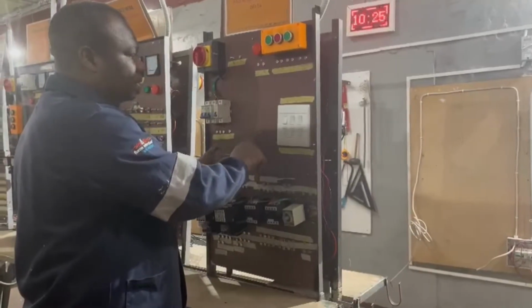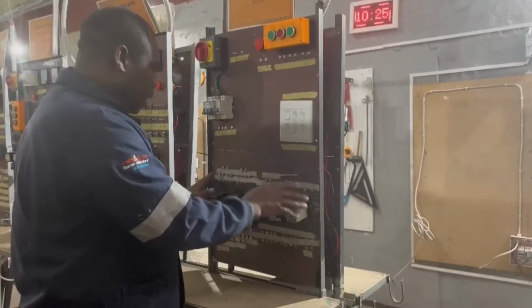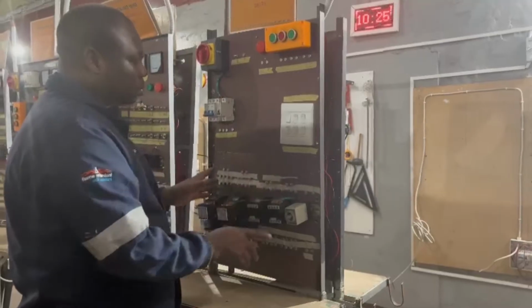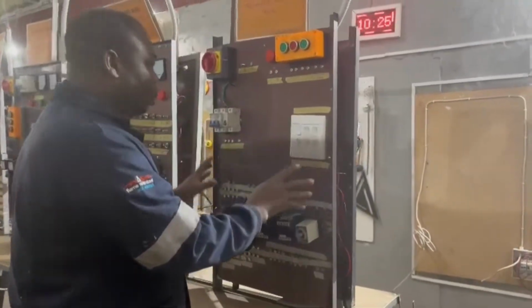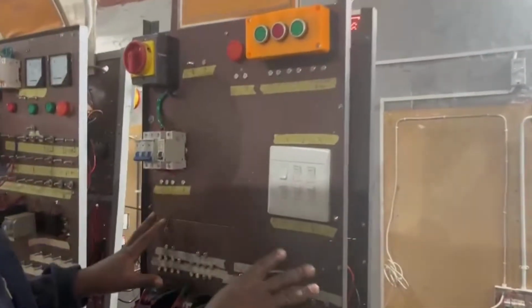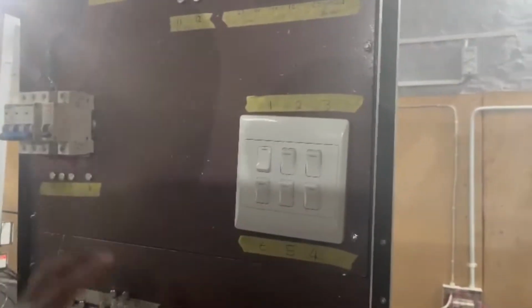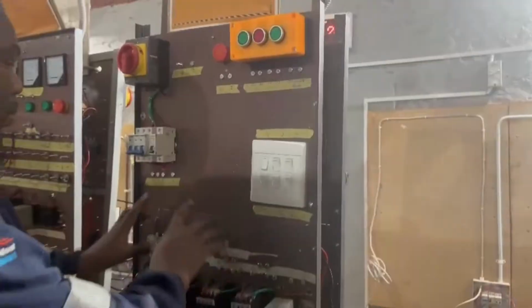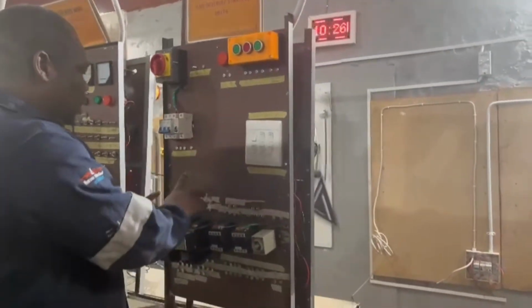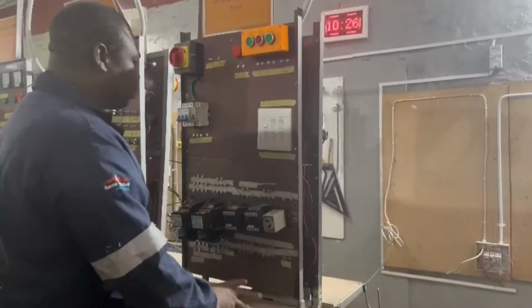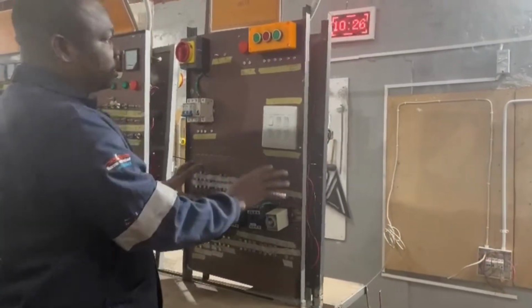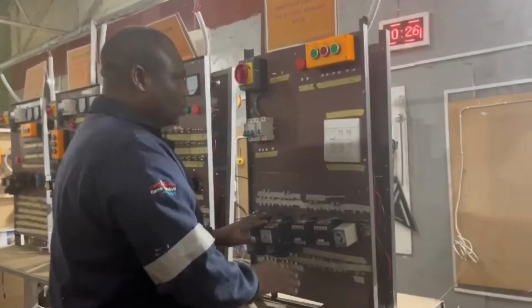So the fault here is just an open circuit fault, whereby when the switch is off, it creates an open circuit, and the assessor will not ask you to find where the fault is. In this session, all you need is to know the principle of fault finding. You should be able to use your multimeter to trace the circuit. You're going to have the circuit diagram, and you have to trace it according to the circuit diagram and find where the switch is.